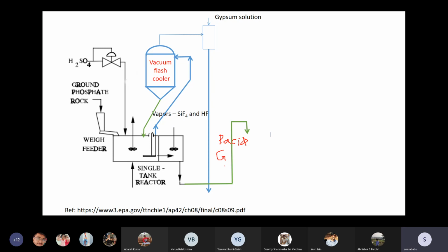So here we're talking about solid-liquid unit operations. Whenever we have solids that need to be separated from liquid, we go for filters. This is almost like a slurry. If gypsum is present as particles, then we might go for a hydrocyclone, but this will be like a slurry. If it is in slurry form, we can never use cyclone separators for the separation. So we prefer the filters.